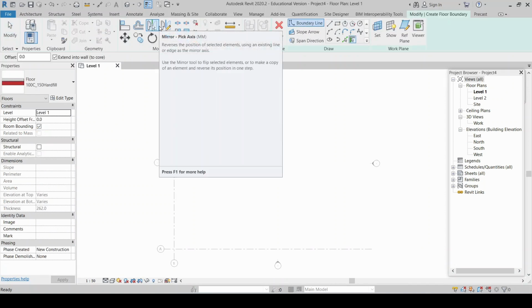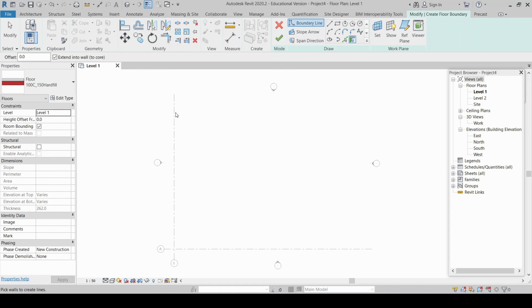When we click on that tool, the tool activates, and you can see that all the other objects in our window have gone grey. We're now in a floor creation tool sandbox. We're effectively away from the rest of the model, and we can create a floor without affecting any other objects within the model. We can still use the other objects in the model for references, and we can attach lines to it, but we're not actually going to change anything other than creating a floor in this mode we're in.